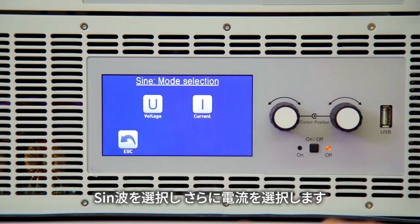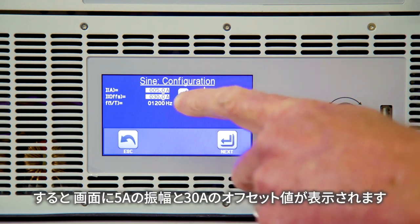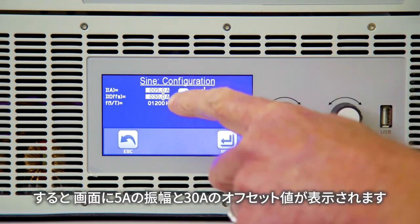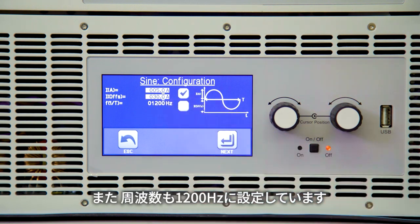What I've done is just selected a sine wave, and I've selected that I want to create current. I want my ripple to be about 5 amps. I want 30 amps of offset, so it's going to drive a fundamental of 30 amps, but then be able to put a 5 amp ripple on it. And I programmed the frequency for this particular case to 1200 hertz.